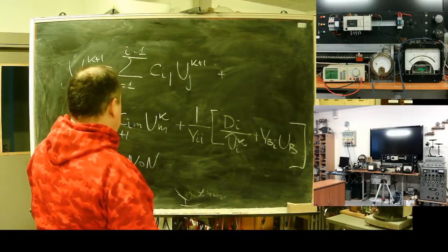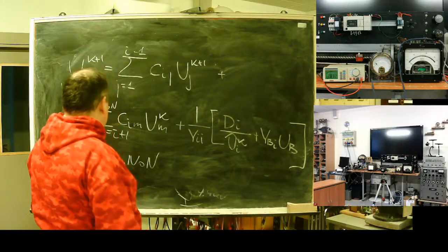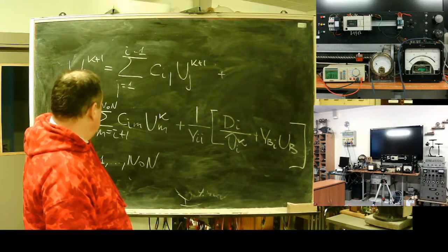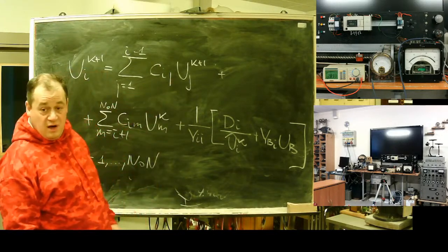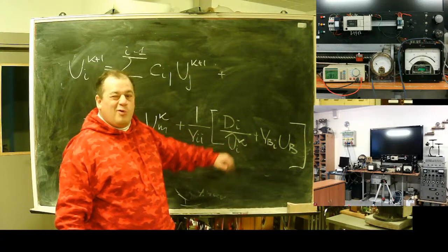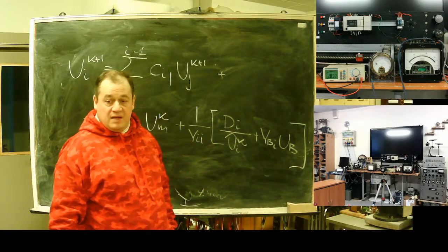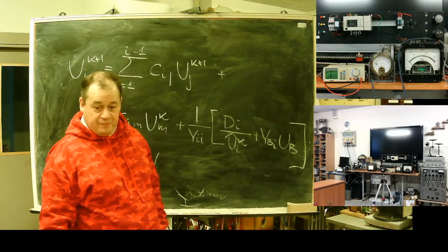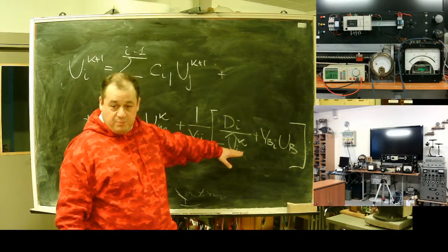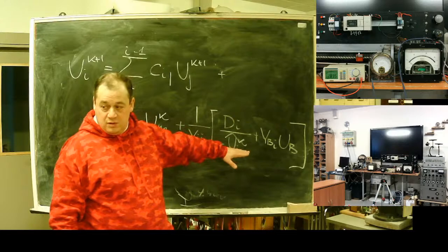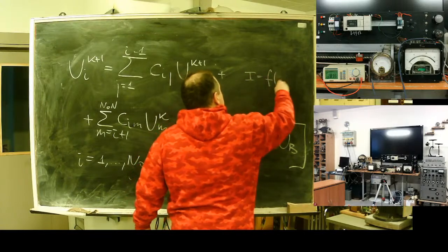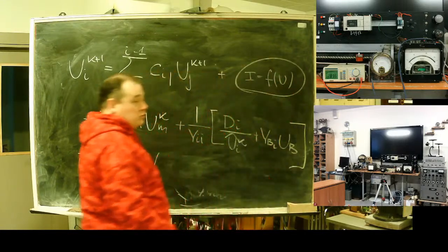So, what we got here is a modified Seidel technique. These two elements are from the classic Seidel technique, and this one we recalculate currents at every step for each voltage estimation, using the previous voltage from the previous step to find current as a function of voltage.